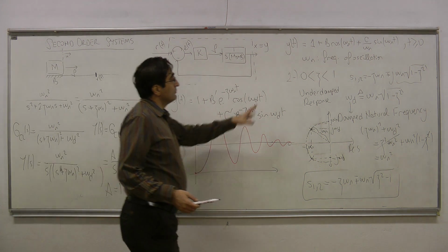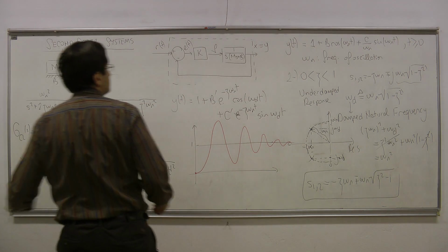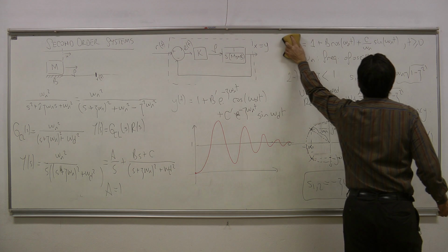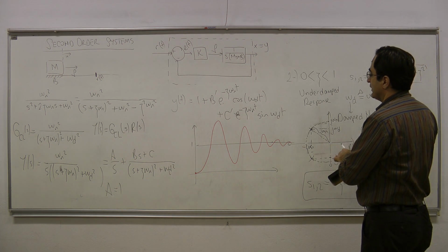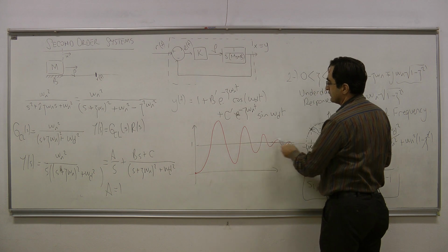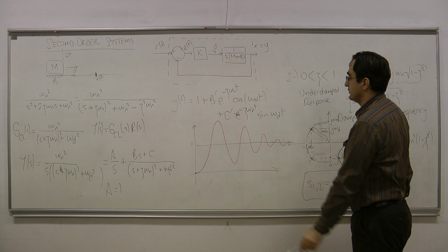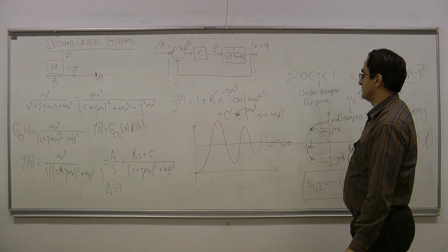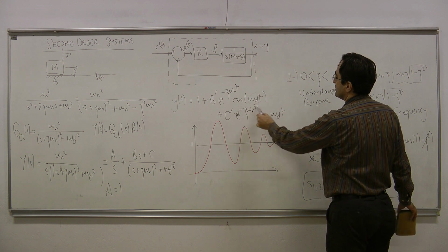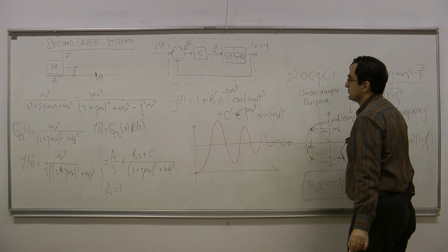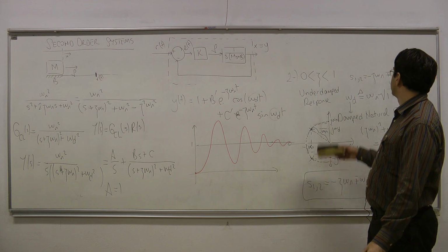So here, then we are going to go into the third case. So one last question here. What is the frequency of the oscillations that we observe here? What is the frequency of oscillations we observe in the underdamped case? Your answer is just in this function. And you see that the oscillation frequency is omega d. And that is what we call the damped natural frequency.